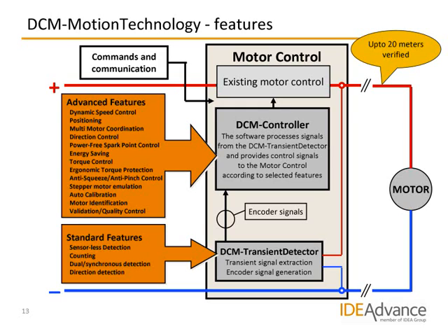Dynamic speed control, where the DCM controller algorithm adjusts the number of commutations or angular steps per time unit. Windscreen wipers, dynamically controlled in relation to car speed, is just one of many applications for this feature. The accuracy of the detection is determined by the number of commutators or poles in the motor. It is therefore possible to emulate a stepper motor with a rotational precision equal to the angle between each pole in the motor. For many stepper motor applications, this will be sufficiently accurate.